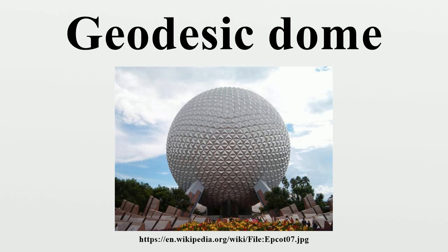The shape of a dome house makes it difficult to conform to code requirements for placement of sewer vents and chimneys. Off-the-shelf building materials normally come in rectangular shapes. Therefore some material may have to be scrapped after cutting rectangles down to triangles, increasing the cost of construction. Fire escapes are problematic. Codes require them for larger structures, and they are expensive. Windows conforming to code can cost anywhere from 5 to 15 times as much as windows in conventional houses.